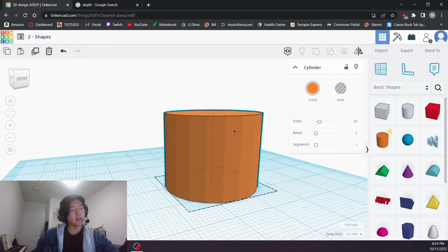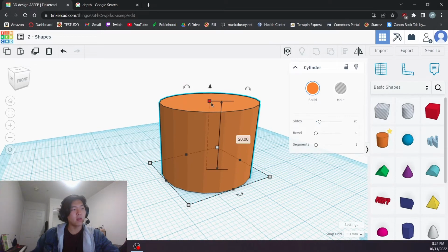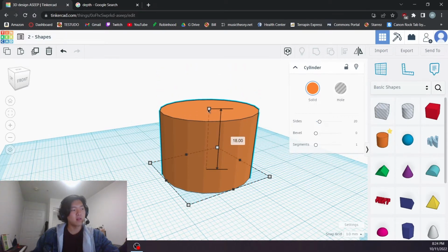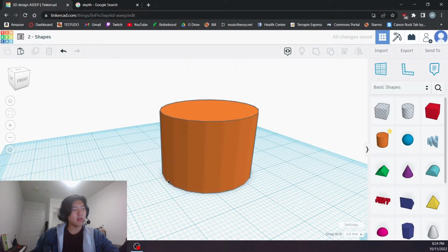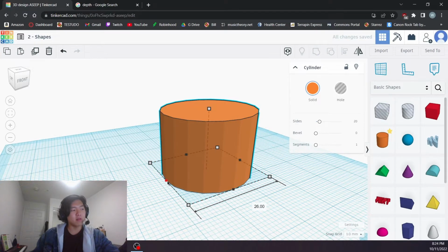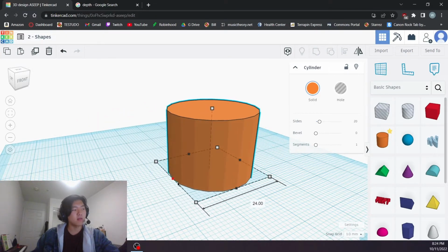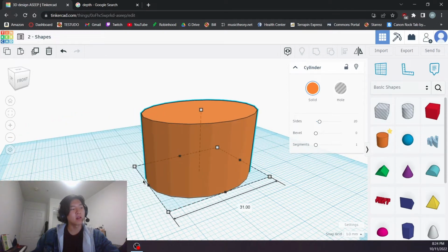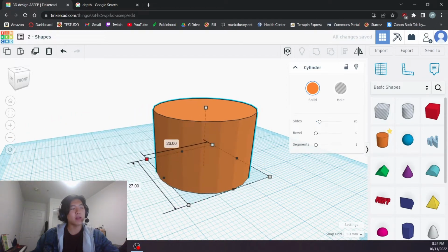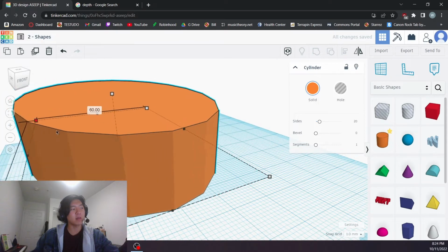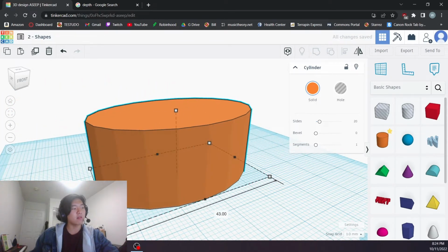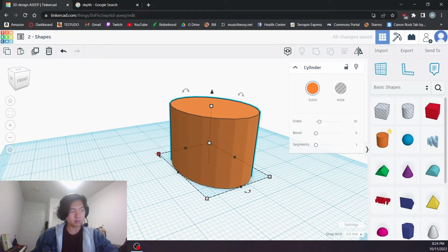This white one above the rest, at the top face of the shape, only allows you to extend the shape vertically in the z-axis. And these black squares do the same thing, in the sense that they only allow you to extend in one direction. With these white squares, if I'm not careful, see how it's getting bigger in both the x and the y, but with this black one, it's only the x.